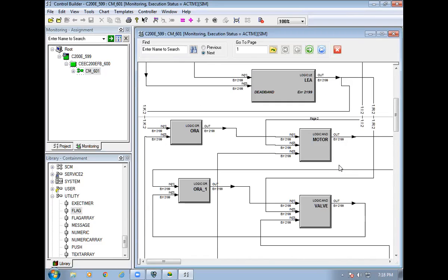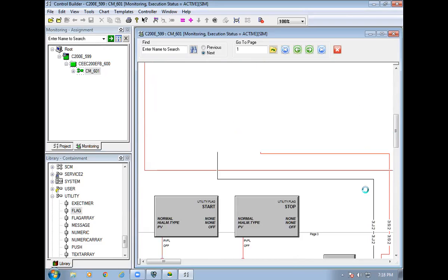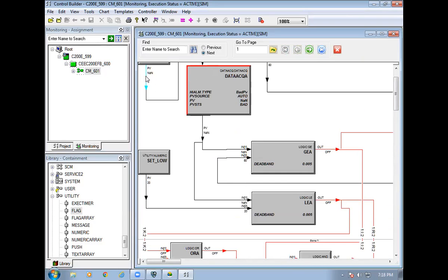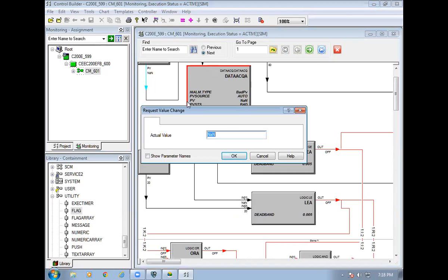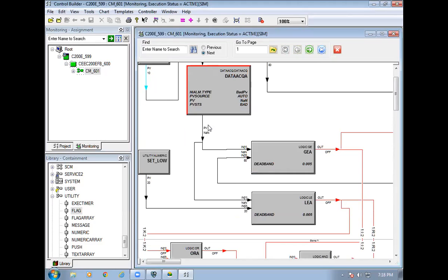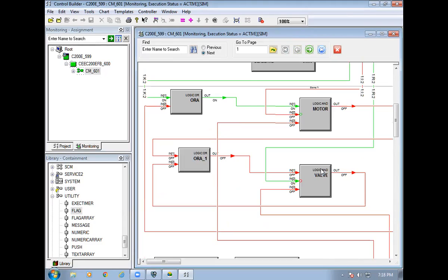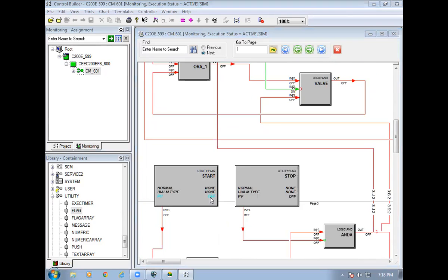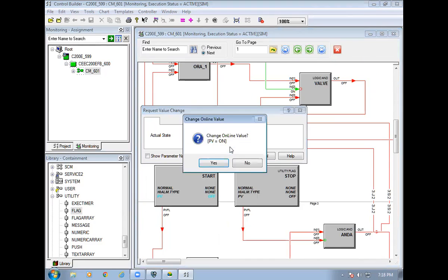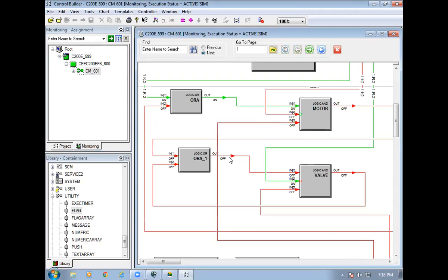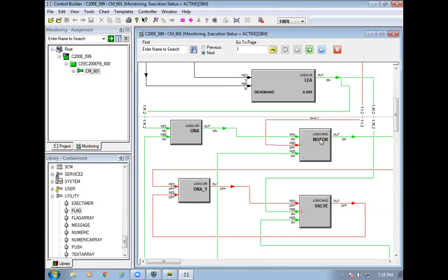So now see, I didn't enable the start and stop here. Suppose the value coming in from the field is 10. So 10 means it is a lesser than block. I need to start a motor, but my motor will not start. So at that time I'm going to give a start here. Then only my motor should start.